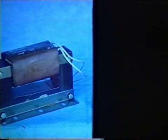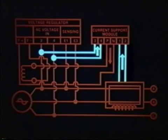The current boost system consists of a static control rectifier assembly and a power current transformer. The control assembly typically receives AC sensing voltage input from the main alternator and current input from the power current transformer, similar to the series boost system.